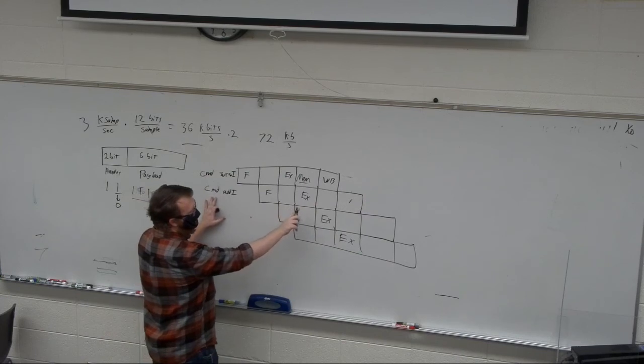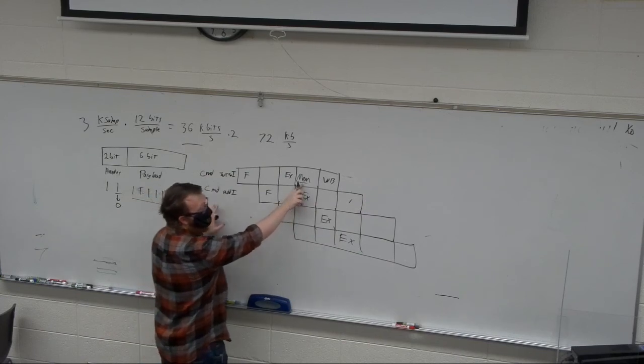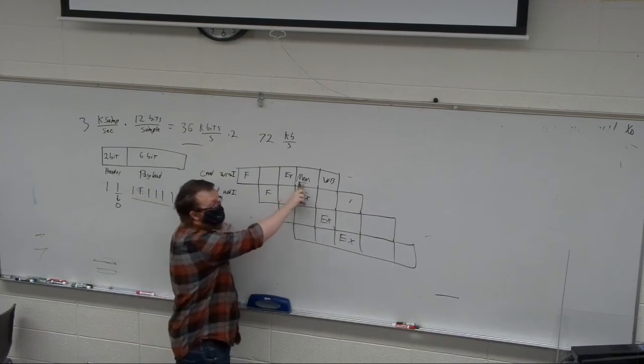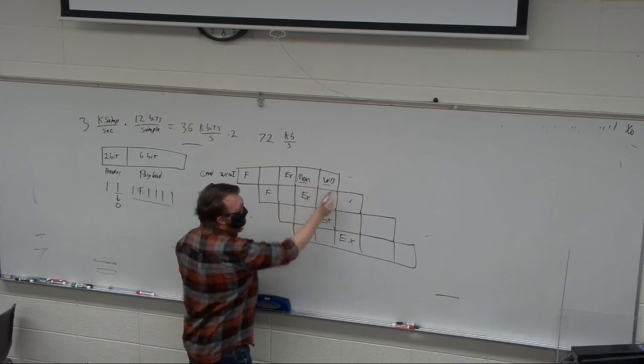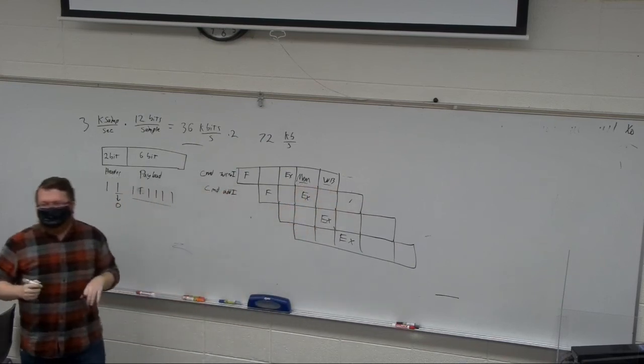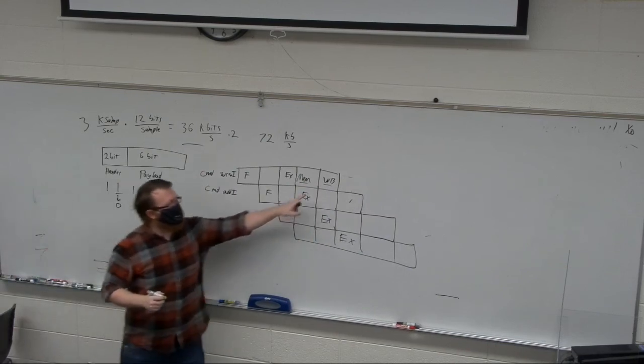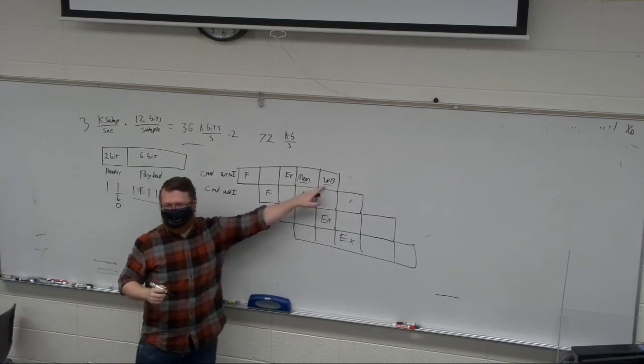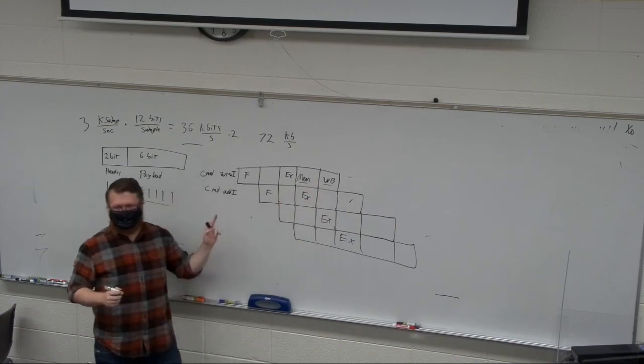That's what you'd be reading from memory too, right? Yeah, I can read or write to memory here. So the write back in what the book is explaining is if I'm not saving it to memory and I'm just loading it from that register, then I feed that back around to the next operation.